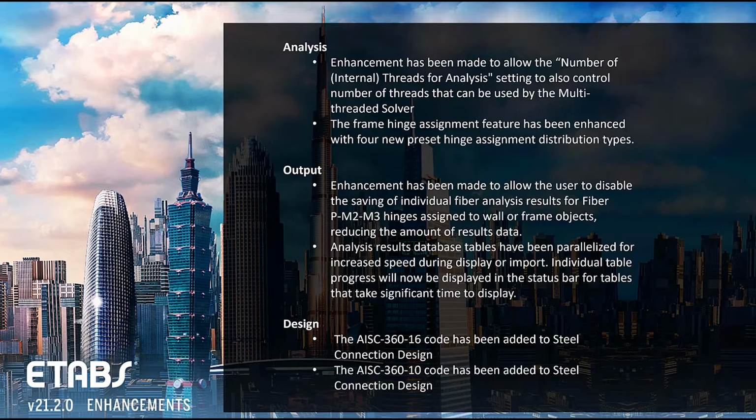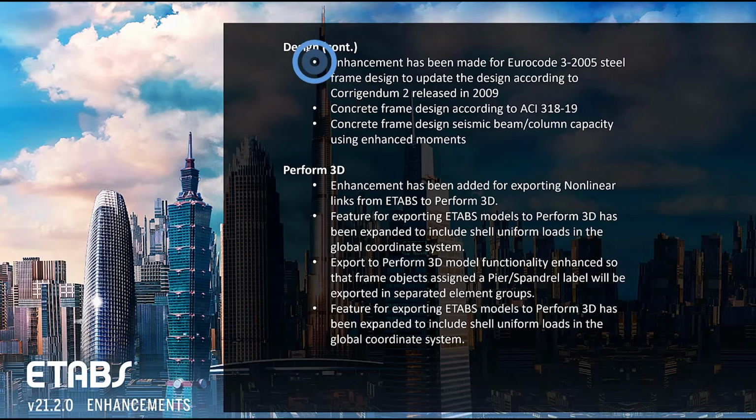New feature in design, the AISC 360-16 code has been added to steel connection design, and we'll go through each one of these. Also included, Eurocode 3-2005 steel frame design updates, concrete frame design for ACI 318-19, as well as concrete frame design seismic beam column capacity using enhanced moments. And we'll also go through the features that have been included for Perform 3D.